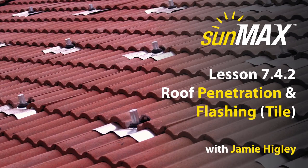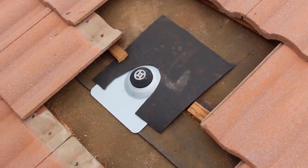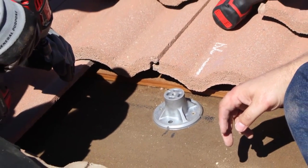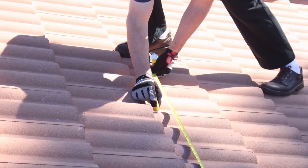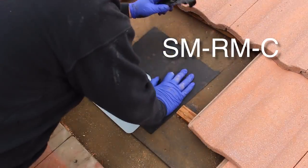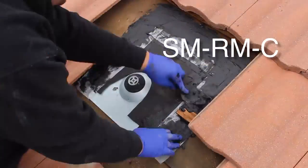Lesson 7.4.2 Roof Penetration and Flashing. Tile. When installing the composite roof mount and flashing, follow the instructions in the previous lessons, including the shingle rooftop flashing video, as you measure, mark, and remove tiles to install roof mounts and the flashing material. It is highly suggested that you apply a layer of roofing sealant and reinforcing material around this standard flashing material